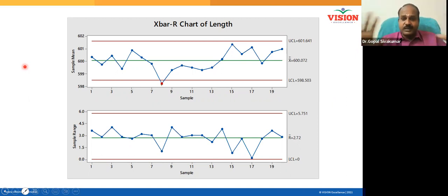But in a company where the processes are not standardized, they will take a sample every single hour. You understand? Because they are not confident that people will follow the procedure. Somebody can change anything they want between hours. And so in those companies, you must take more samples. The sampling frequency will be very high. Do you understand? And obviously it will add up to your cost. Hope I have answered your question.